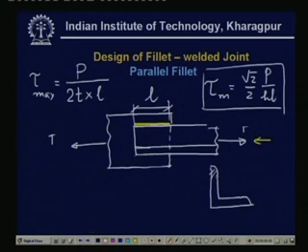So, this is the cross section of the plate. This plate cross section is here. We have the center of gravity somewhere here. So, this is the center of gravity, and now if you apply similar joints on both sides, again because of the asymmetry of the structure, there will be bending stress developed. So, we will have to make two different lanes of the welding now.